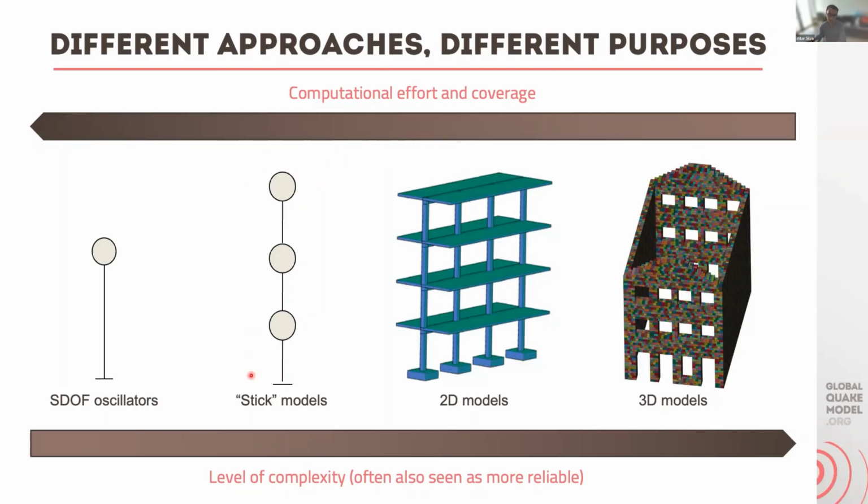But we thought that at least as a next step, why not use the stick models or the fishbone models or the stick and mesh models? They have been used. I'm by no means saying that this is a scientific novelty. They have been used for many years. There are a few publications, even from the World Conference I think in Lisbon in 2012, that were already mentioning these models. But it's still an approximation, but it allows us to do perhaps a slightly better modeling of the different EDPs on the different floors. And this is what we're doing right now.